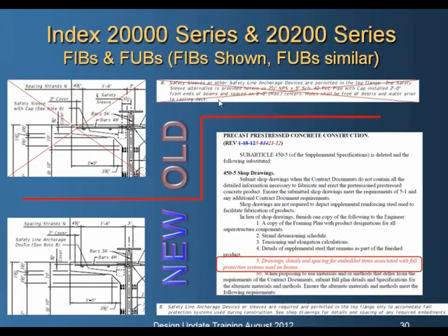However, we've had calls from suppliers of safety devices asking us how they're supposed to incorporate their system into this. This is a contractor's means and methods, therefore we should not be specifying this in the standards. So we've modified it to only show a representation of a safety line anchorage device, and we've modified the note, as you can see here, so that the device or sleeves are required and permitted in the top flange only to accommodate fall protection systems during construction.